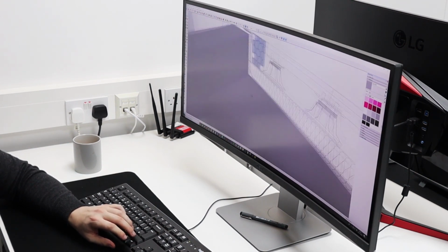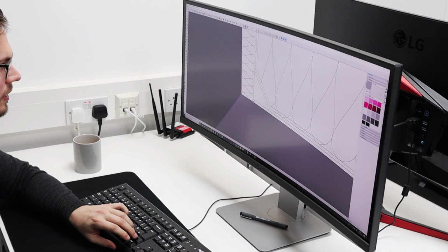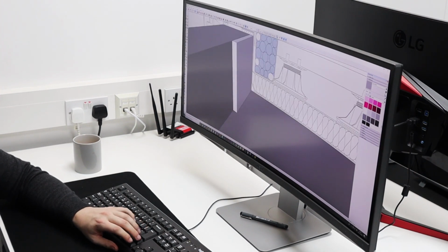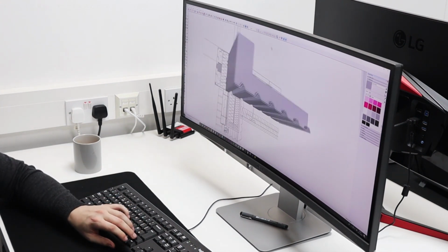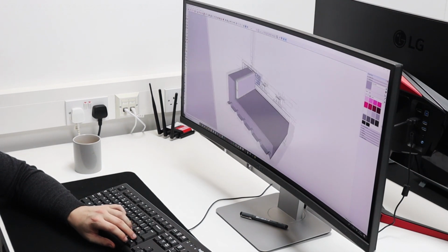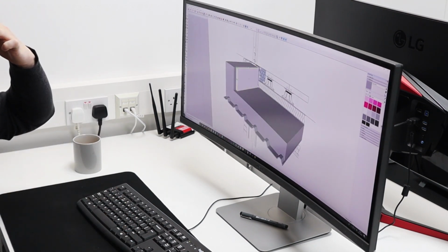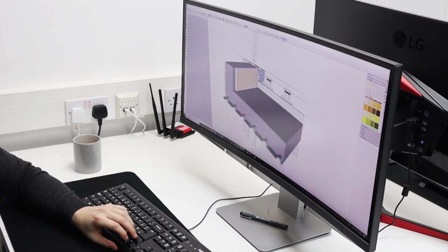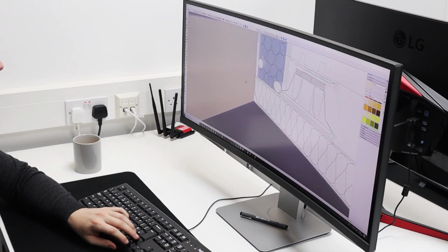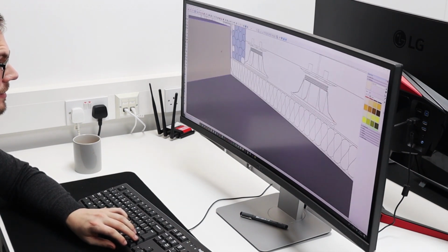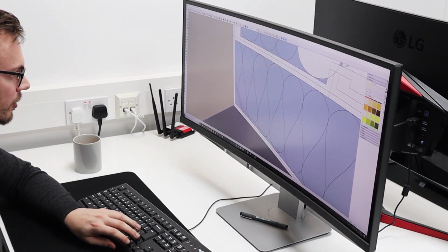So we've got that. Then we've got a bit of perimeter insulation there, just a little bit of extra protection against thermal bridging going through that upstand. Let's give insulation a little yellowy colour. Then we've got our main roof insulation here, that's doing the bulk of the work thermal wise.